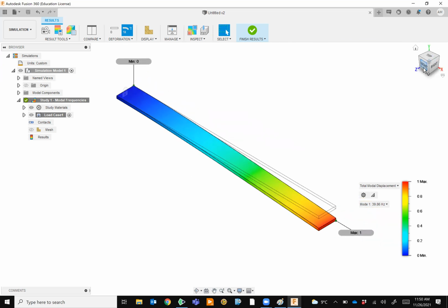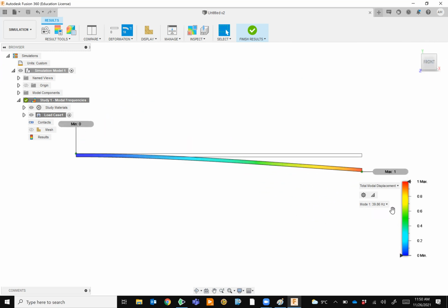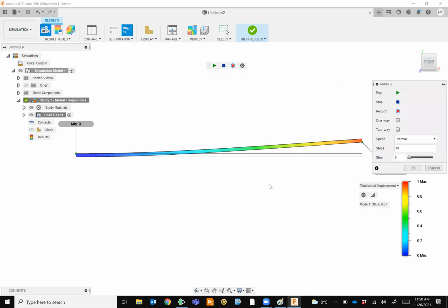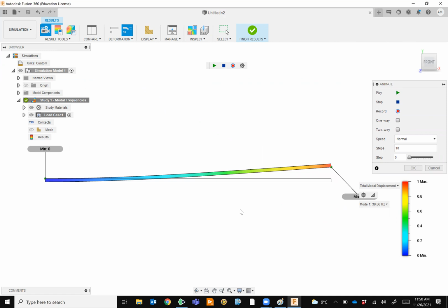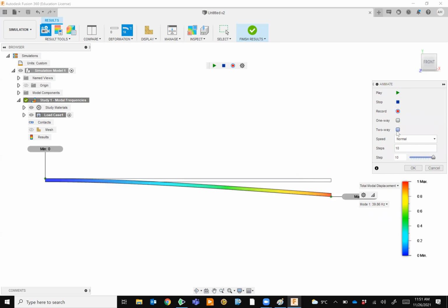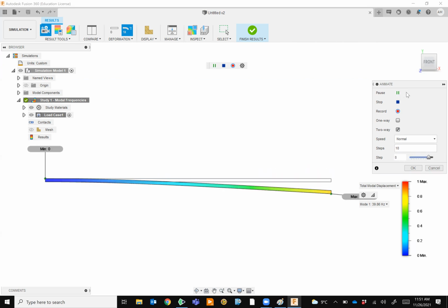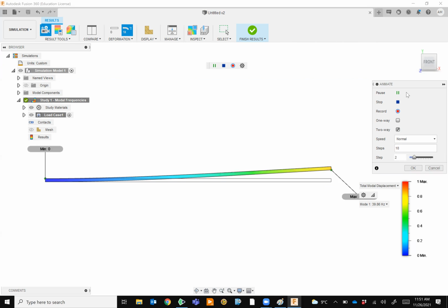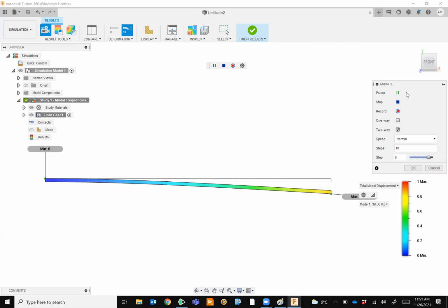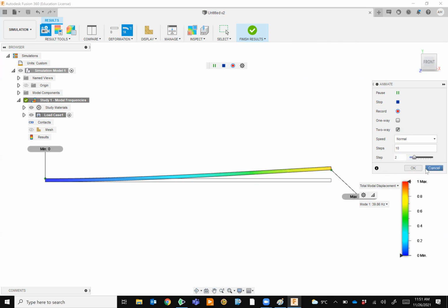All right, this is my first mode. And the software gives me its natural frequency. It is 1.39 hertz, depends on the material and the cross section. It is important, guys, please stay with me in class for 2 more minutes, so you have an easier time following the math. So this is the first mode. Of course, it's a slow motion, and that's the shape of the first mode and the natural frequency that the software is giving me.